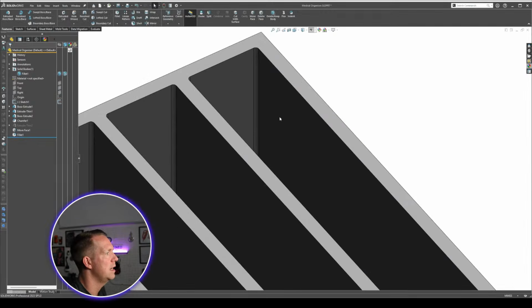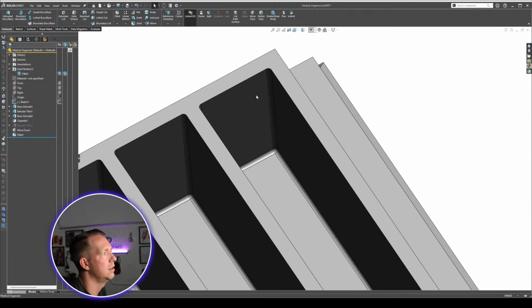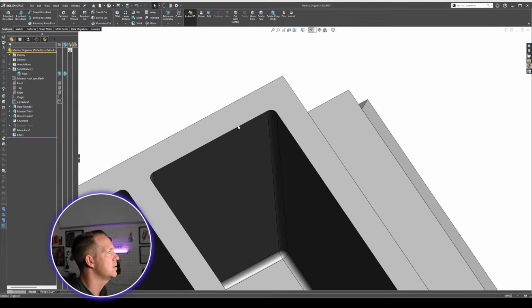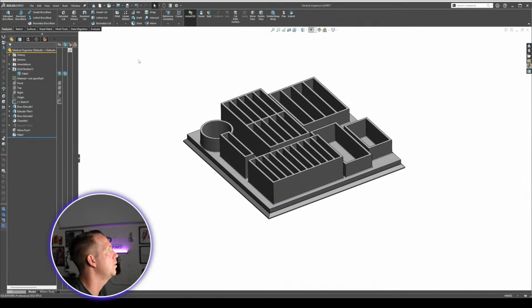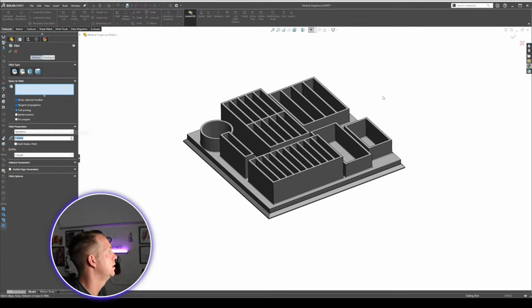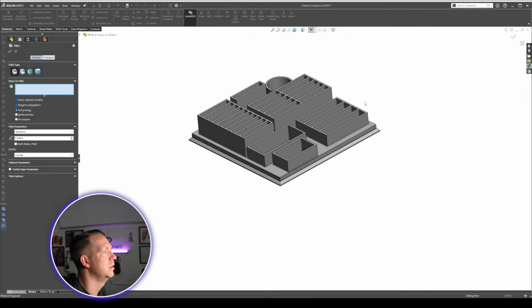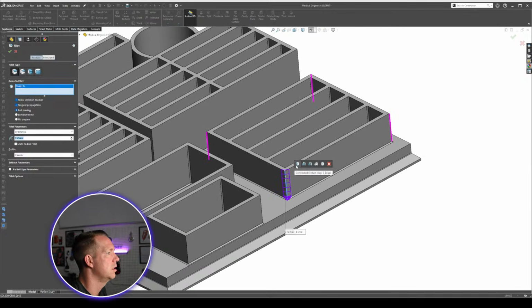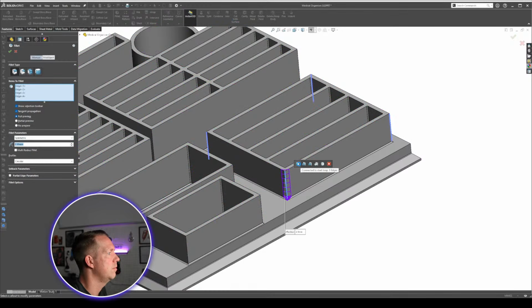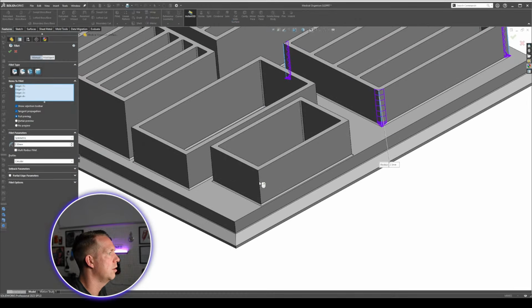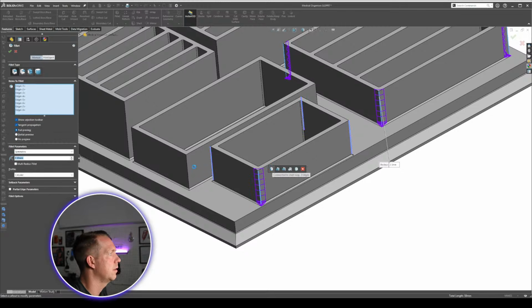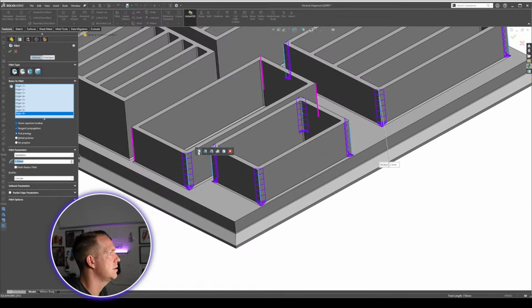All right, so if we have a look at what it's done, all my inset edges for me. Just a small radius. And the reason I want to do a small radius here is because I'm going to do a bigger one on the outside. All our thicknesses here are 2 millimeters. So on the outside edges, we're going to put in a 2.5 mil radius. So I'm going to go fillet 2.5 mil. I'm going to select an edge, and I'm just going to look through my previews again to see what comes up. I don't want any of those options, so I'm just going to go to connected to start loop, and I'm going to do a few of these. All right, so I'm just getting the outsides.